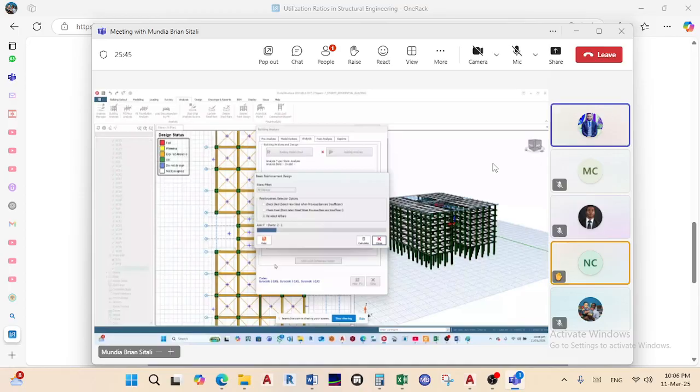We're coming back to it. Remember I said in a typical design, you first change the section, then you come and add the area of reinforcement, because the area of reinforcement is usually also a factor of the section size of the member. So after this, we're going to the reinforcement, then we adjust what reinforcement we want to work in there.